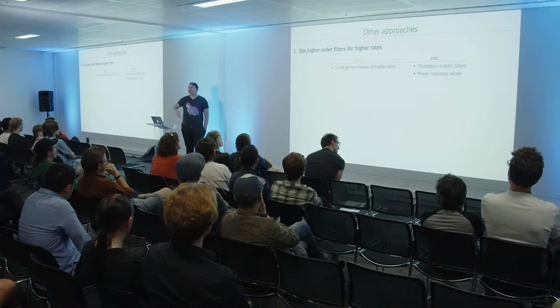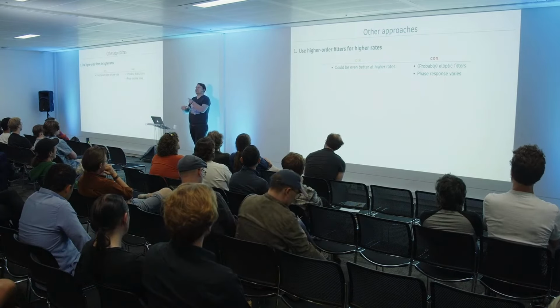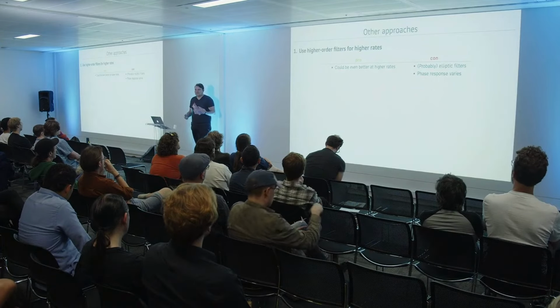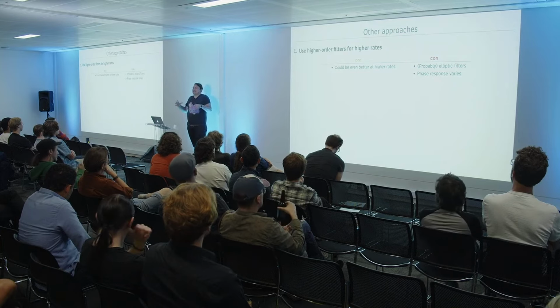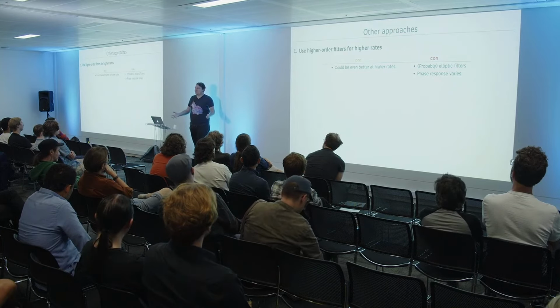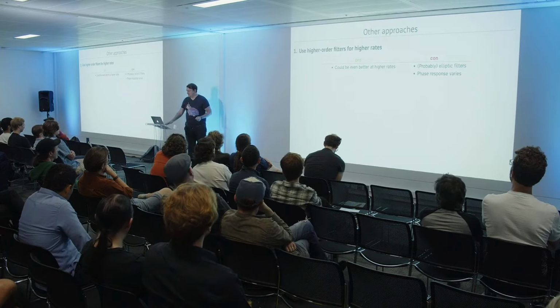And also, if you change the order and other characteristics, the ripple and so on, then your phase response changes. Maybe this is no issue, but I have seen people who are using the Hilbert filter inside feedback delays and that kind of thing, inside phaser-like structures, and there the phase response ends up being part of the sound. And so when that shifts around, you're actually in trouble.